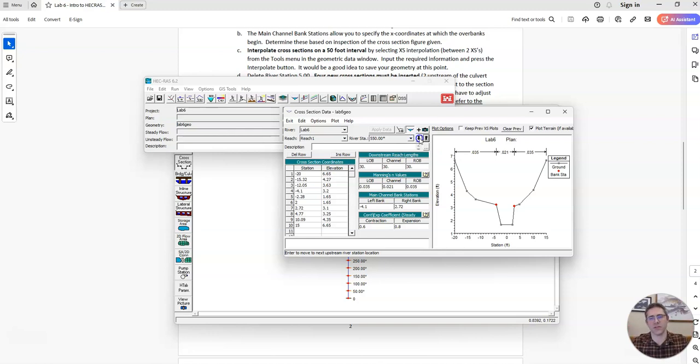So you'll see, 550 and 520, they have the exact same cross-section. Not just the same geometry, but the same elevations. But we want, as water flows downstream, for it to be going downhill, so we want lower elevations as we go down. So what we normally need to do is figure out what the slope was and then interpolate and so forth.